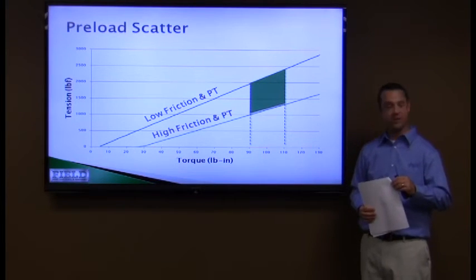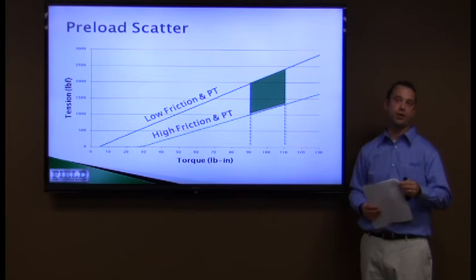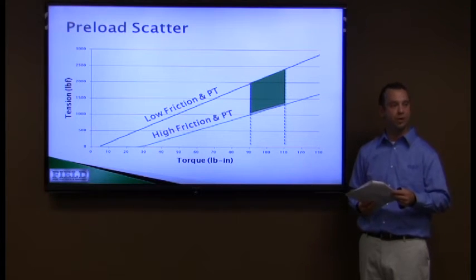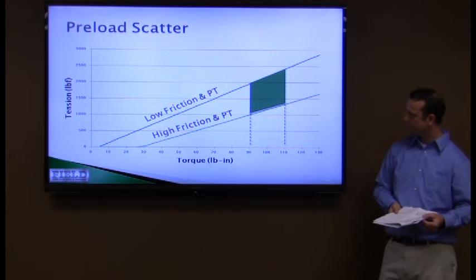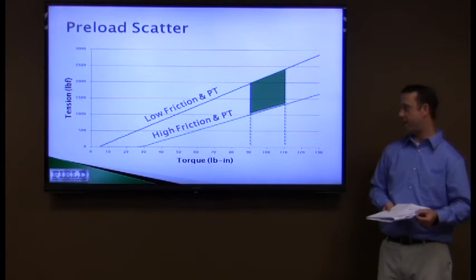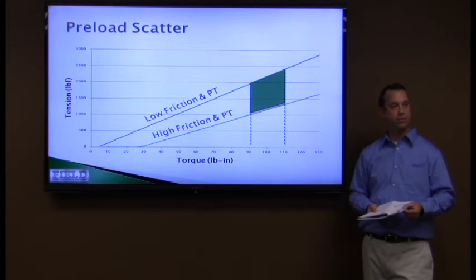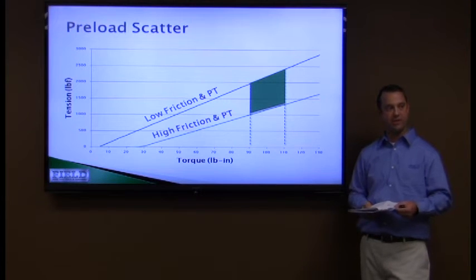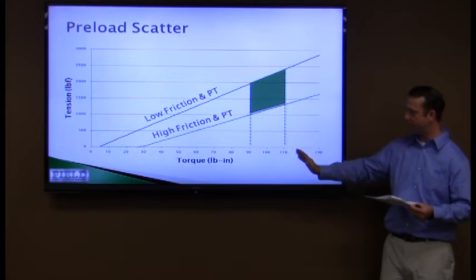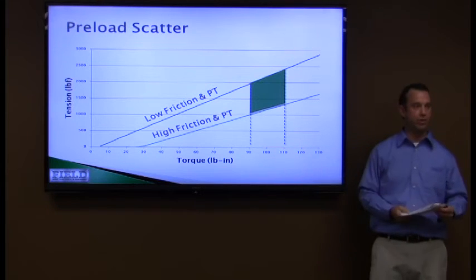Is that torque control then? Not necessarily. It depends. Your torque control is going to be dependent on your assembly method and your assembly tools. Right? The torque control would depend on what your method is right there. If you have a torque-to-yield kind of gun, I would say this would be excessive for that. For a handheld torque wrench, that's probably in the ballpark.